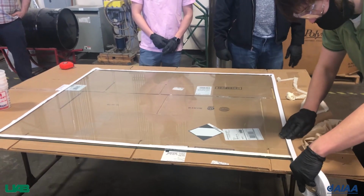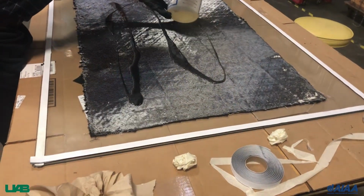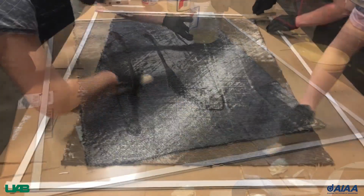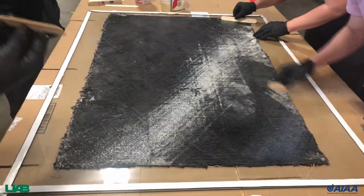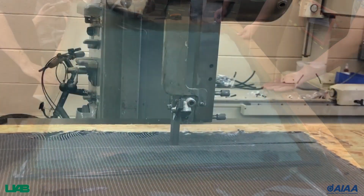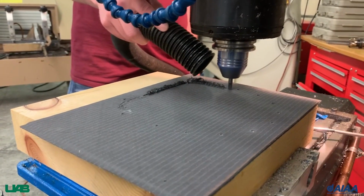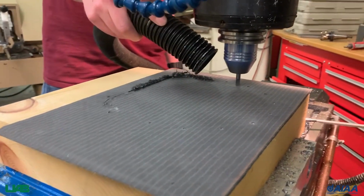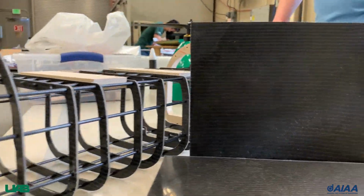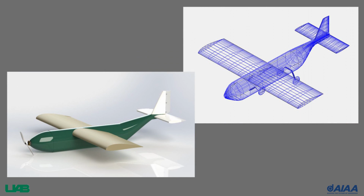The wing and the stabilizer were manufactured from balsa, basswood, and carbon fiber tubes. The SD7062 wing had a 5-foot wingspan, 1.3 foot chord, and weighs 2.4 pounds. The horizontal stabilizer had a NACA 12 airfoil, a 24.7 inch span, and an 8.2 inch chord. The vertical stabilizer had a taper of 0.4, a 9.5 inch span, and a 6.3 inch average chord length. The total tail assembly weighs 2.3 pounds.